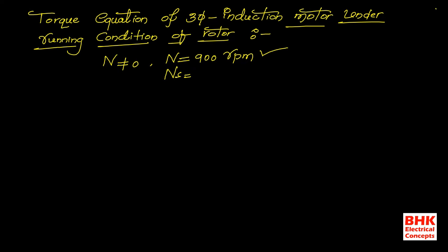That is the reason why the formula we use to calculate the synchronous speed of an induction motor is 120F divided by P. Clear? So now coming to the point.